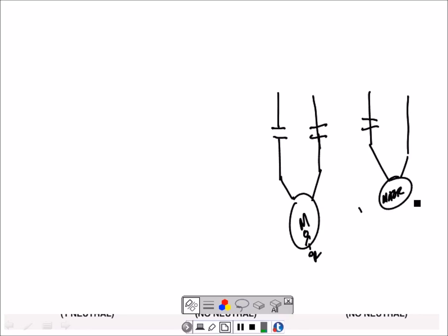Well, by George, you better pull the disconnect on this thing, because if this right here is open, the motor's not going to run because it doesn't have a complete path. But this line right here is still going to be electrically hot even when the motor's turned off, because this voltage is going to go through the windings in the motor, and it's going to be sitting right there. So there's going to be 240 volts on both leads of the motor even when the motor's not running.